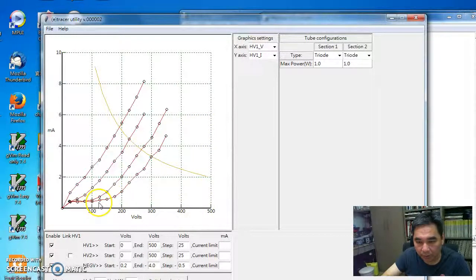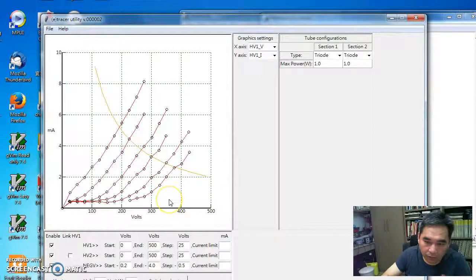Okay, here is probably another problem I need to solve, but it's not that important at this moment. It looks like there is a DC drift, a measurement drift here. I think if we perform some calibration, we can resolve this problem. As you can see, the curves are usable now, and we can derive the gain and impedance by using these data points.